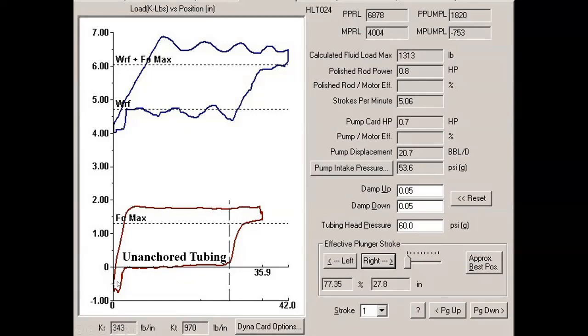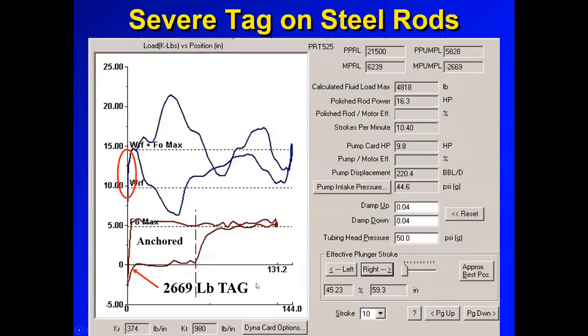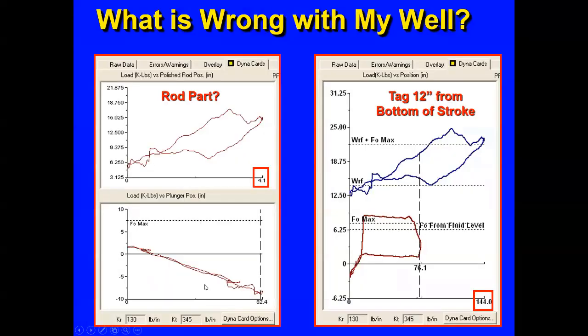And we have a pump tagging down. This is the point of this slide. It's showing a hard pump tagging down, and that pump needs to be respaced. Another pump tagging close to 2,700 pounds. Here we can see that peak or spike at the surface, but you see the pump tagging down really hard, maybe due to that incomplete pump fillage.